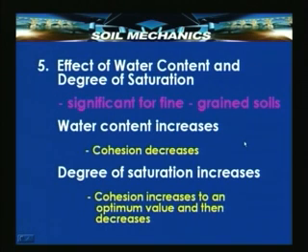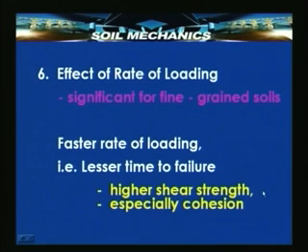When the water content increases, cohesion decreases. When the degree of saturation increases also, the cohesion increases to an optimum value and then decreases. The rate of loading is extremely important because the so-called drained or undrained conditions is a relative term, as I have stressed in the last lecture.